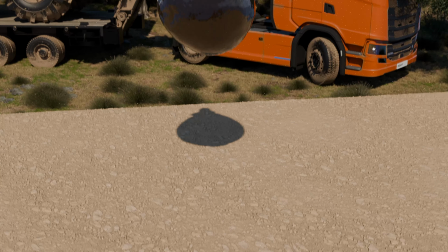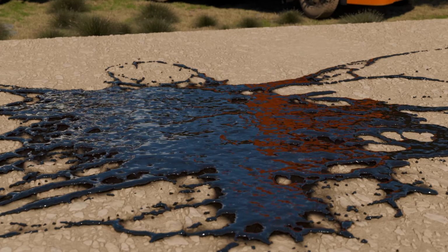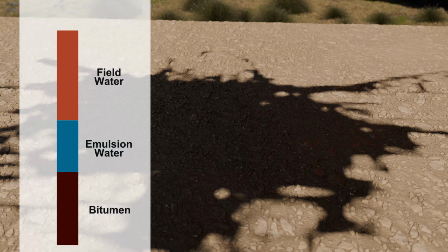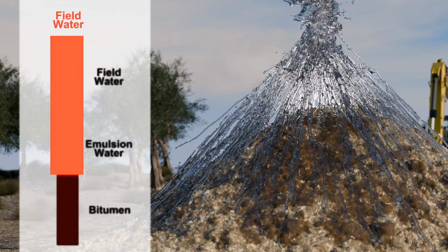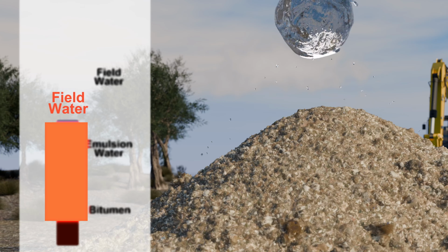Conversely, adding bitumen emulsion to dry material can result in a flash break, as the emulsion's water component is absorbed too quickly by the dry hydrophilic fines. The ideal condition is when the moisture content of the material to be treated is at 50% of its optimum moisture content.